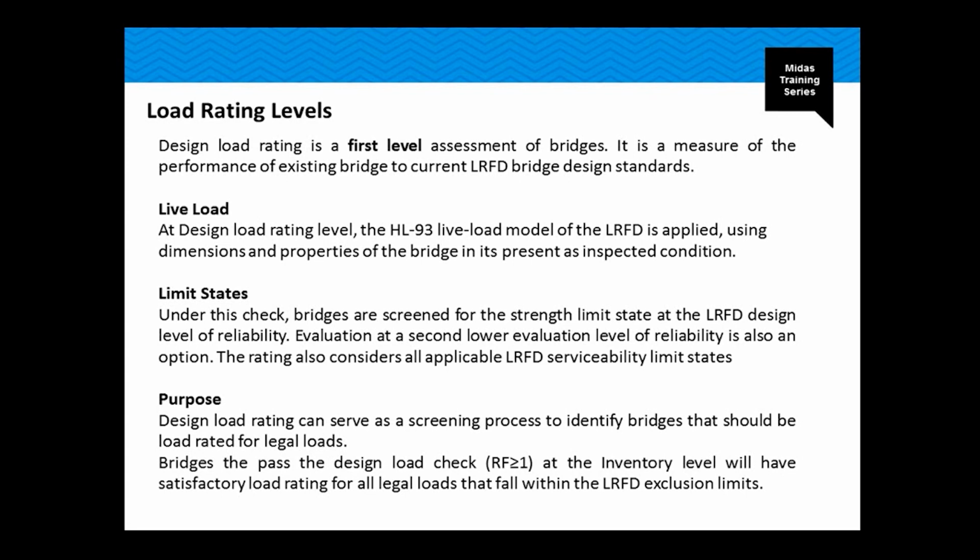As you see, this one is very standardized as per the LRFD bridge design standards. The evaluation at a second level of reliability is also an option for this first level load rating, and the rating also considers all applicable LRFD serviceability limit states. The purpose of this one is that it can serve as a screening process to identify bridges that should be load rated for legal loads, that should be evaluated basically.